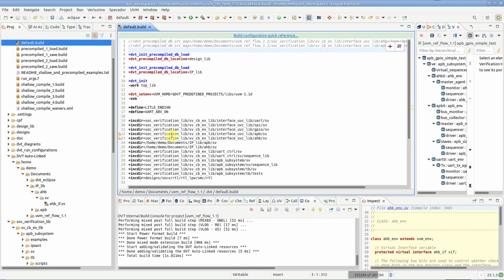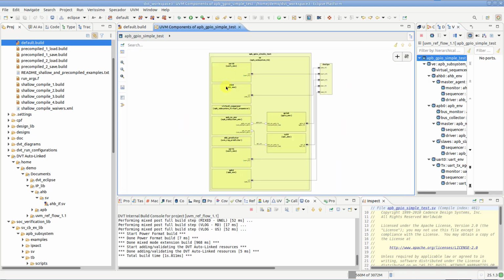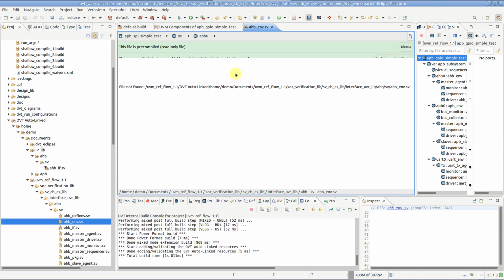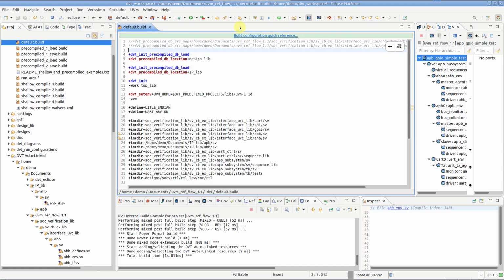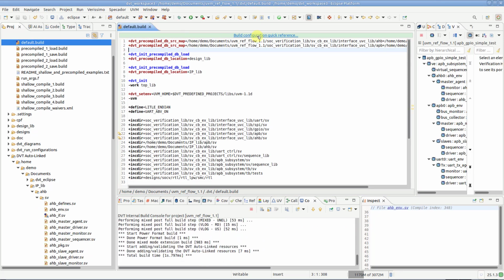You can seamlessly browse and navigate around the project, for example in DVT views or diagrams, even if precompiled source files are not available at load time. DVT will automatically pick up the source files if they're exactly in the same location as when precompilation was performed. If not, for example when files are checked out to a user-specific location from a version control system, you can use this dedicated directive to remap their paths.